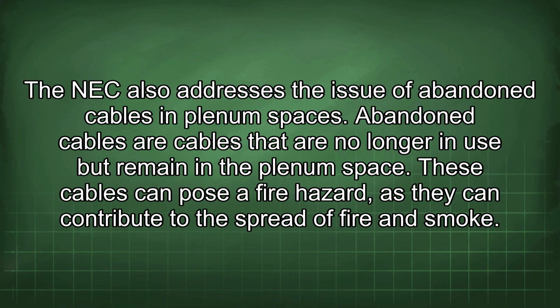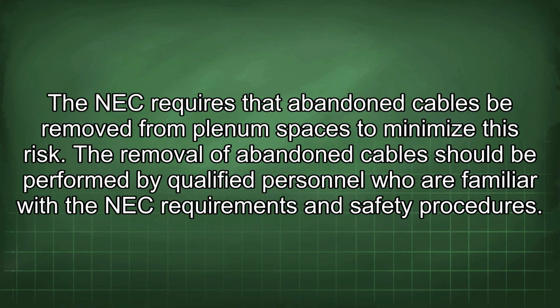The NEC also addresses the issue of abandoned cables in plenum spaces. Abandoned cables are cables that are no longer in use but remain in the plenum space. These cables can pose a fire hazard, as they can contribute to the spread of fire and smoke. The NEC requires that abandoned cables be removed from plenum spaces to minimize this risk. The removal of abandoned cables should be performed by qualified personnel who are familiar with the NEC requirements and safety procedures.